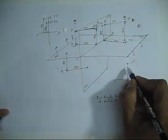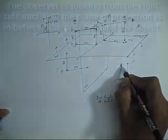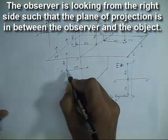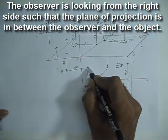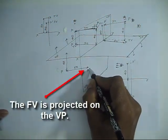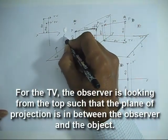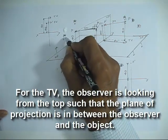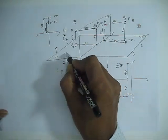So now the observer is looking from the right side for the front view, and the plane of projection is in between the object and the observer. So the front view is made on the VP at this spot. For the top view, the observer is looking from the top. Plane of projection is in between the object and the observer. Again, this is the top view.